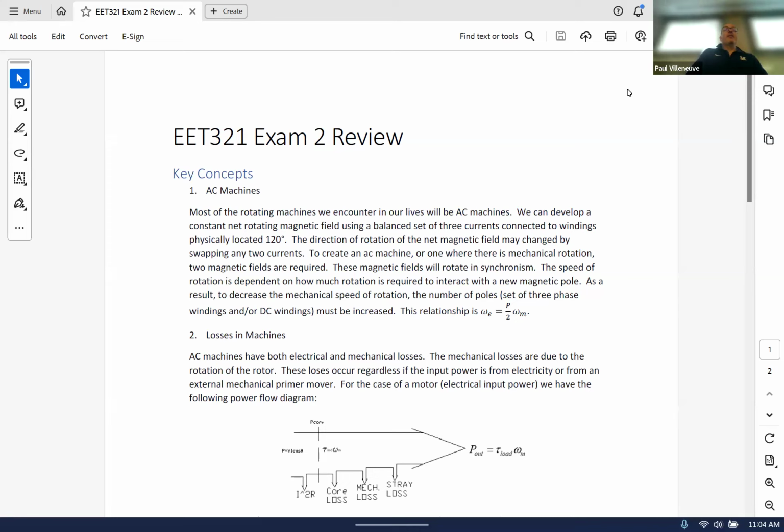So the stator winding was just physically stationary. We had 3 windings because we're talking about three-phase machines. And the first ones we looked at were mechanically spaced 120 degrees apart. Remember, a winding has an in and an out. So the ends were all 120 degrees out of phase from one another.